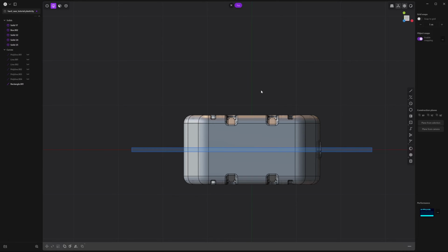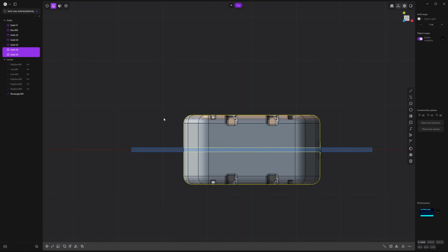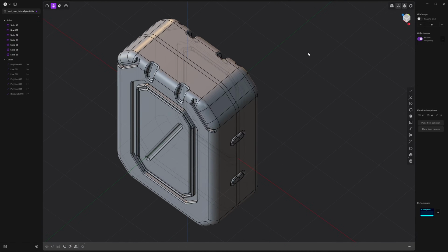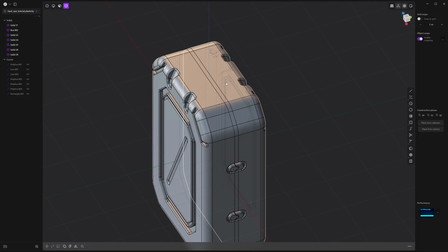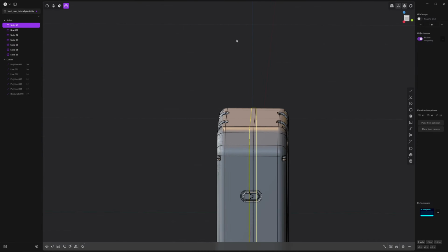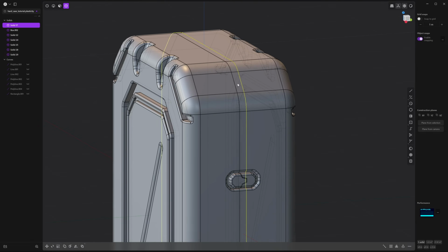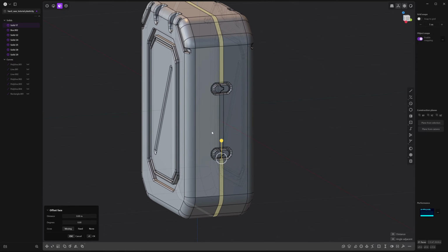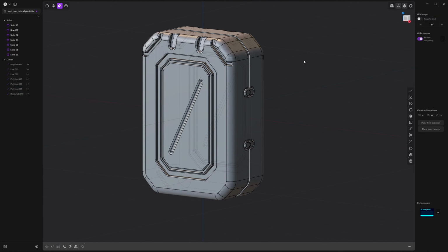Right click to accept, and now press C. Select your main body, and then select this curve, and right click to accept. Now let's hide this curve, so select that curve by pressing 2 and selecting it, pressing H. Now you'll see that that curve went right through the whole body and created this shape here. Press 3 and then alt click this outer edge. And move it in. Just create a bit of a difference there.